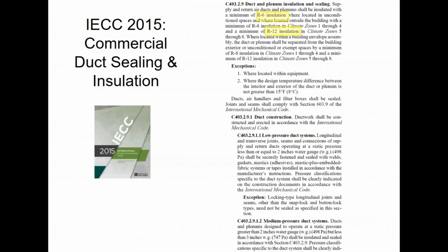First of all, insulation. The insulation needs to be an R6 level if it's in an unconditioned space. Right? So I know what that would be exactly. You have to read the definition, but it could probably be like if you had a little bank job and the duct was running through like some kind of attic type area, something like that. Right? If you're going to run the ductwork outside, like true outside, you need R12 insulation. Right? This is what's required for energy code.